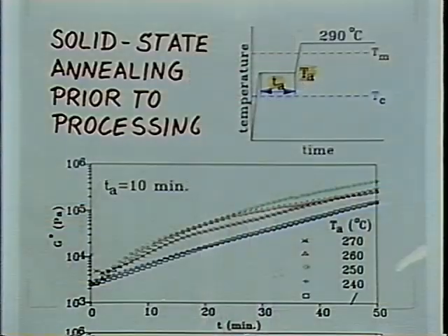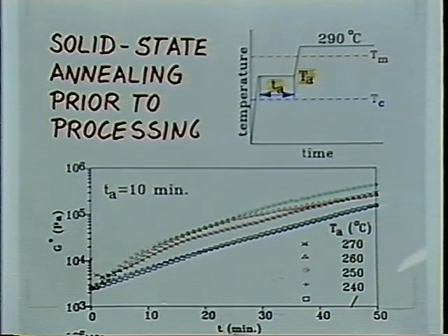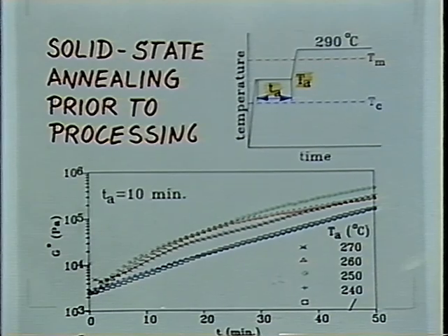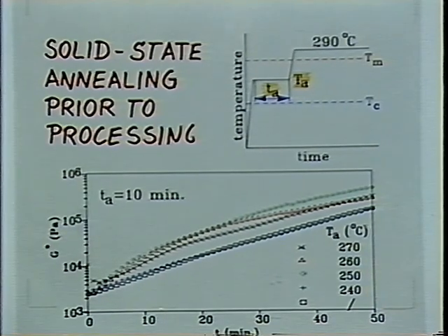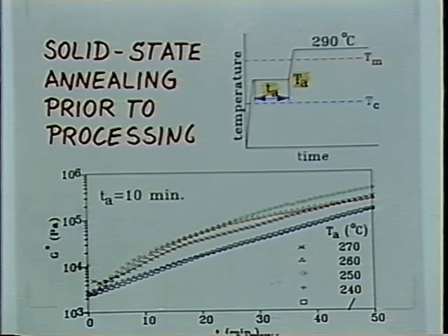We overcome that by choosing this prehistory. We could change this phenomenon further by annealing the sample in the solid state. So even before doing rheology, we would anneal the sample and increase the molecular order in that system. This phenomenon has been studied extensively by Blackwell and by Windle, who looked at the order in those materials and produced very highly ordered liquid crystal samples with fiber spinning and annealing.